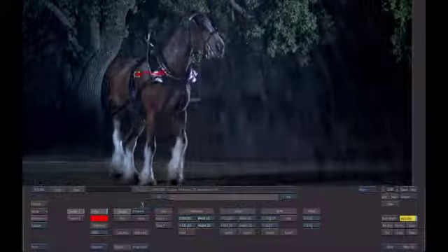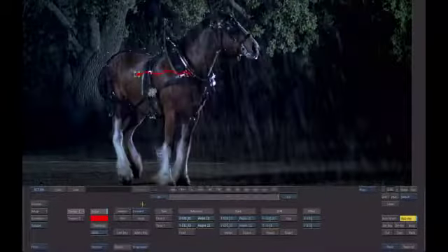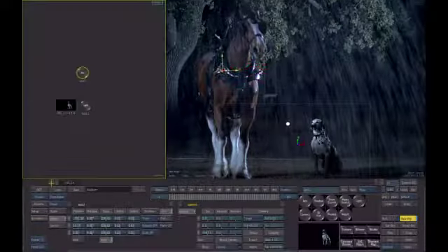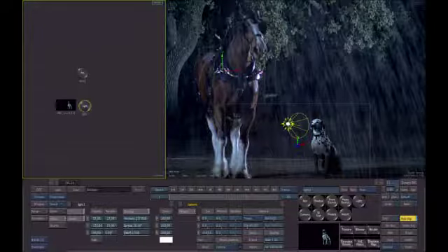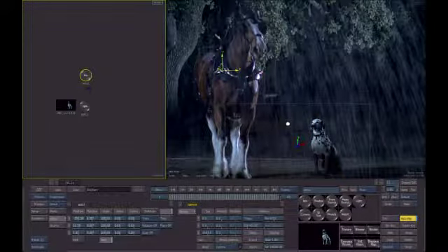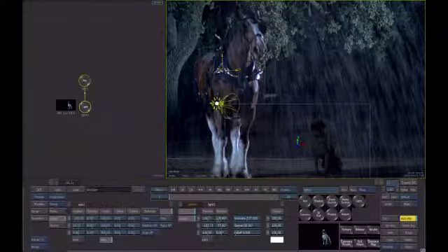So what I've done while Marc-André was explaining is I want that light to appear to be in the scene. I want it to have some relation to the scene. So I just added another axis, and you can see I went into Smoke's schematic here so I can see all the different elements in my composite. We'll see a more complicated schematic in a second. And I just did a quick track, and then here's the light. So once I parent these together, now this light is actually going to inherit that motion.